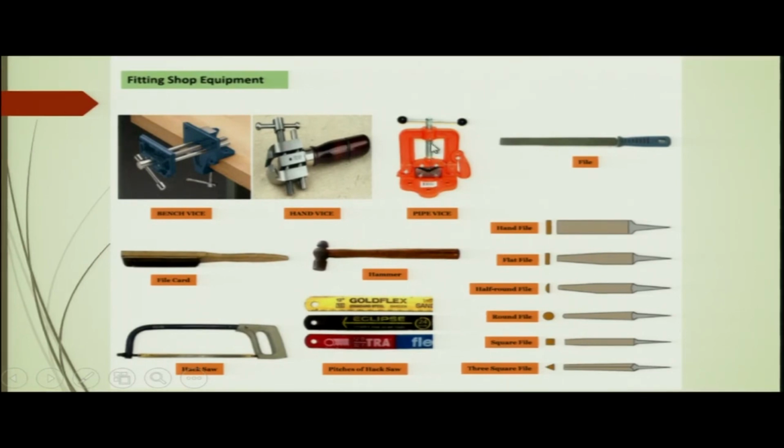This jaw will go up and down, and within this space there is an attachment for the pipe. Okay. These two attachments are rigidly fixed with the base and with the movable jaw, and within this fixture the pipe will be clamped by rotating this handle, and the pipe can be cut or the thread can be made on this pipe.